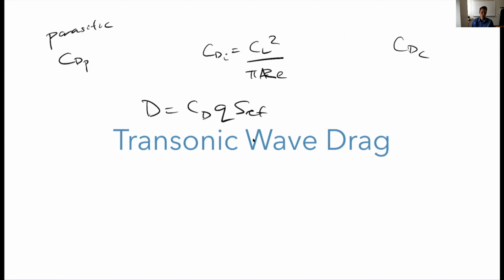It's not going to change too much usually. Induced drag coefficient is a function of the lift coefficient. So if we're at constant lift, relatively constant Reynolds number, those are going to be constant. What about compressibility drag coefficient? Since these are all non-dimensional numbers, right? They depend on non-dimensional numbers.